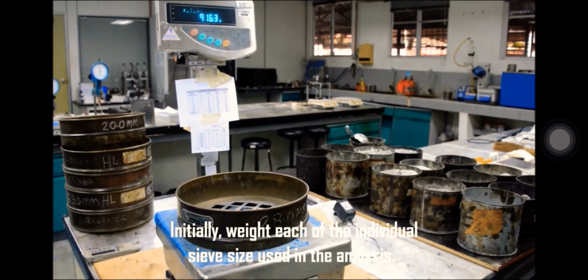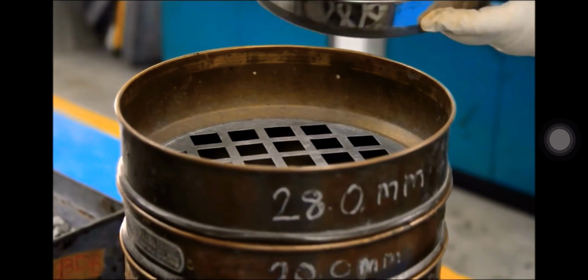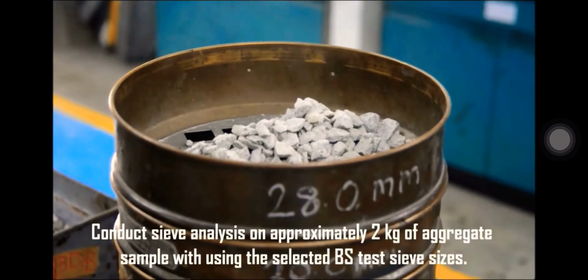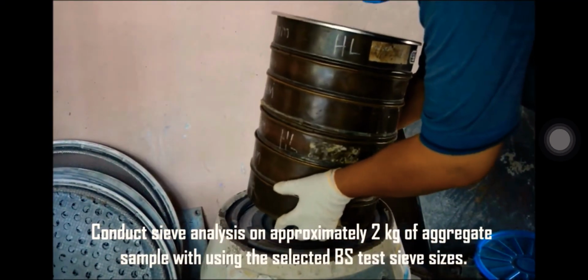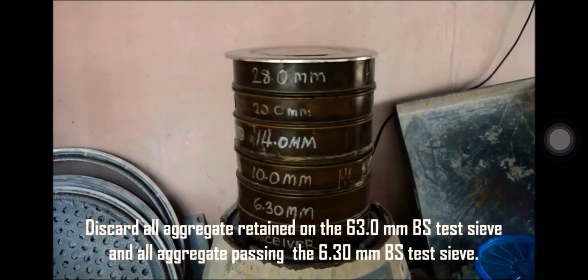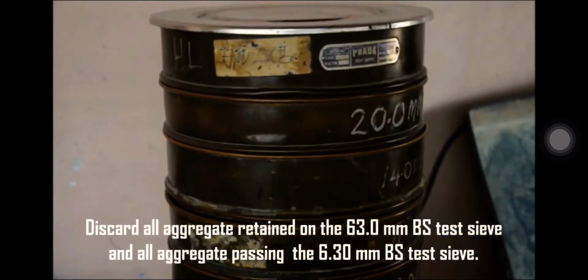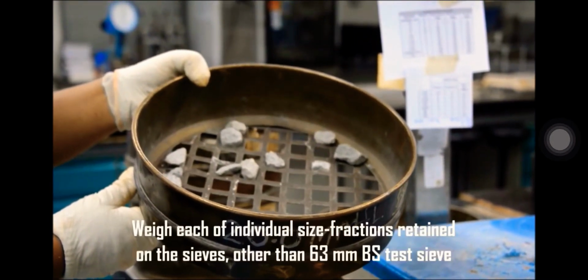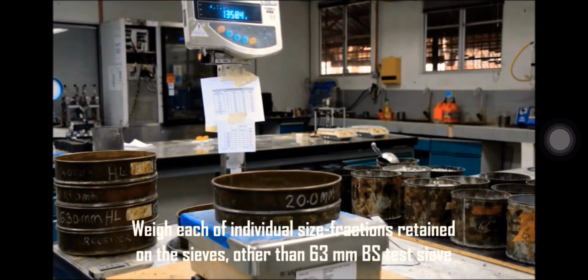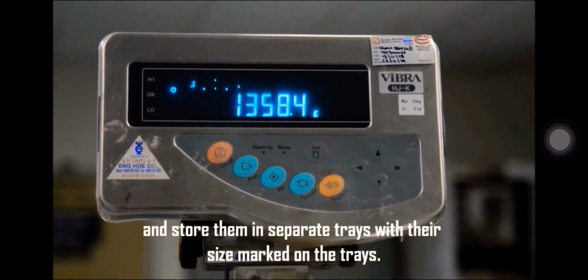Initially, weigh each of the individual sieve sizes used in the analysis. Secure a representative sample of aggregate. Conduct sieve analysis on approximately 2 kilograms of aggregate sample using the selected BS test sieve sizes. Discard all aggregate retained on the 63.0 mm BS test sieve and all aggregate passing the 6.30 mm BS test sieve. Weigh each of the individual size fractions retained on the sieves other than the 63 mm BS test sieve and store them in separate trays with their size marked on the trays.